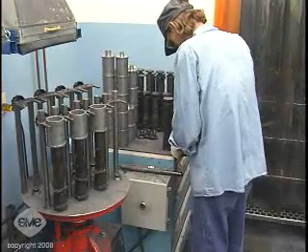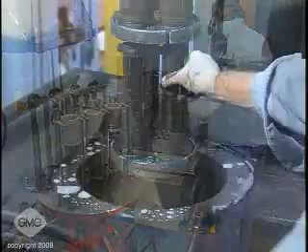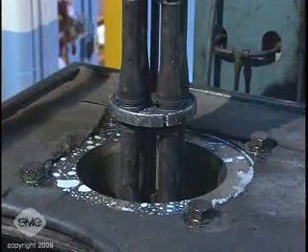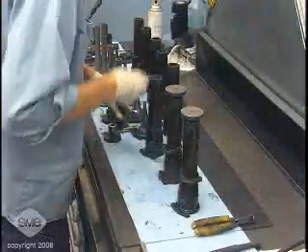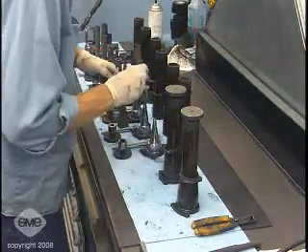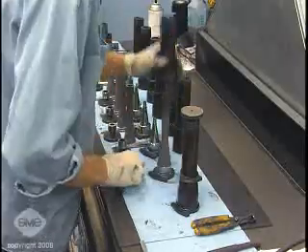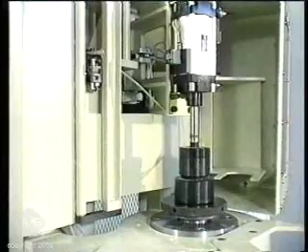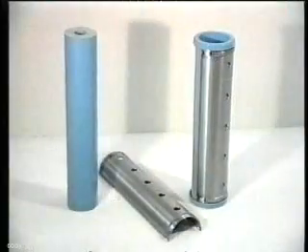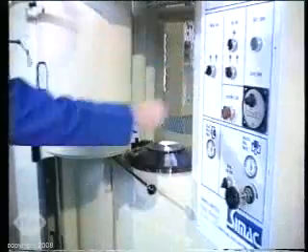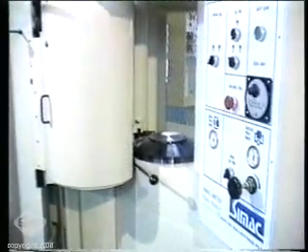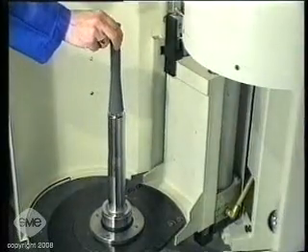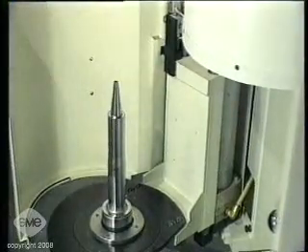Removable molds are filled and sealed outside the press, then immersed in the fluid and pressurized. After consolidation and depressurization, removable molds are stripped from the part. This is called the wet bag process. Fixed molds are filled and sealed within the press, and the pressure is applied behind a membrane integral with the mold. The bottom closure lowers to remove the part after pressing. Because the fluid never touches the mold, this is called the dry bag process.